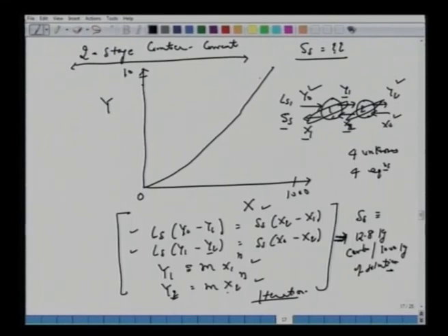Okay. So as we have seen in the earlier also, start with say y0, and here we have y2. So these are the 2 points known to us. X0 is known to us. So we can start from here. Let's say y2, which is 0.96, and this is 0 here. So this coordinate is y2 x0. Now we know the incoming concentration, which is 9.6. But we do not know the amount of the solvent.